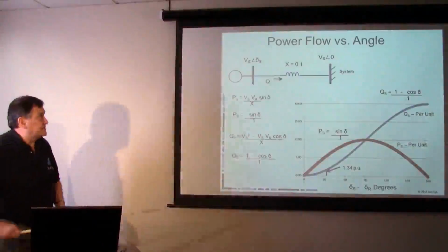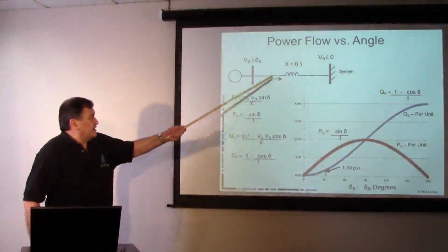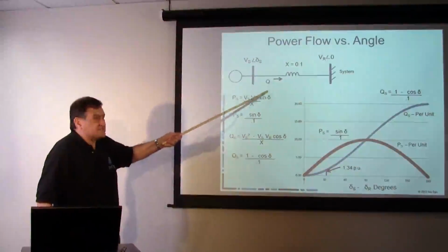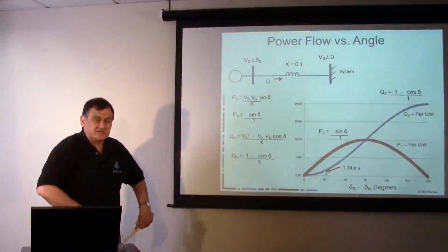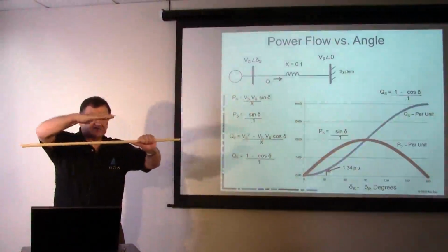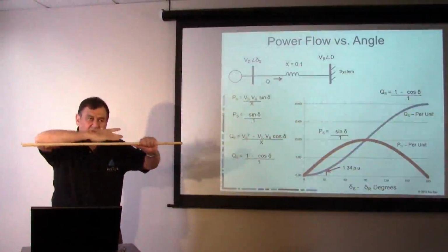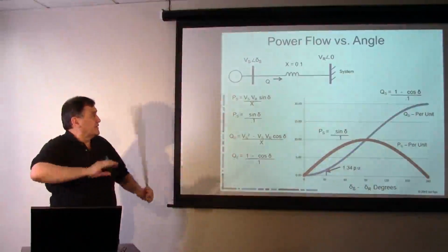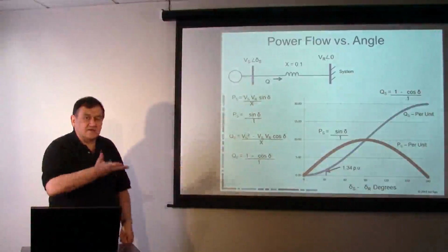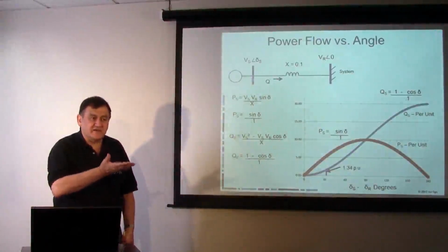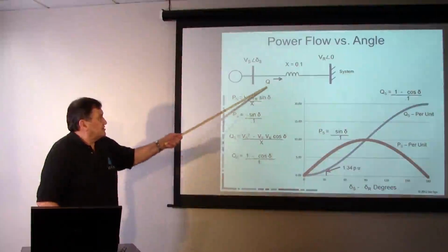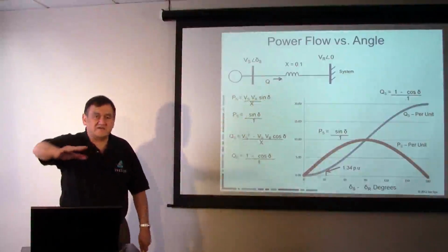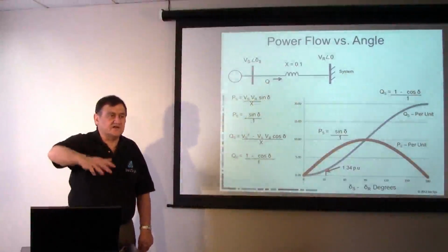This is a simplification. A transmission line actually has a capacitance because those conductors have a physical spacing. You can build up a charge on one conductor versus another. So based upon the voltage, you can get more and more megavars generated out of that line. So at light loads, it can be like a capacitor, but then at heavy loads, it turns into a very dominant inductive load.